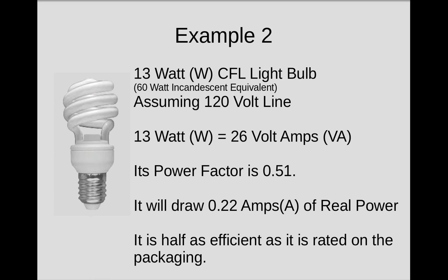You'll notice that they don't have any LEDs recommended. None of them are recommending LED light bulbs, when in fact they are usually a very high rated power factor, drawing 13 watts, normally 13 volt amps. I just kind of wonder at what point, with everybody swapping these light bulbs out, that your power companies are all going to come back to you and say, you're buying 1,000 kilowatts from me. You're only paying for 1,000 kilowatts, but it's actually taken me twice as much money to provide that 1,000 kilowatts to you, and we're either going to have to charge you because your power factor is bad, like we do businesses, or I'm going to have to significantly increase your electric bill because you're actually requiring more amperage from me and you're paying me less money, because that's the way all of our meters are rated. It's just something to think about. I'm not saying that's going to happen tomorrow. I wouldn't be surprised if it happens soon, though.